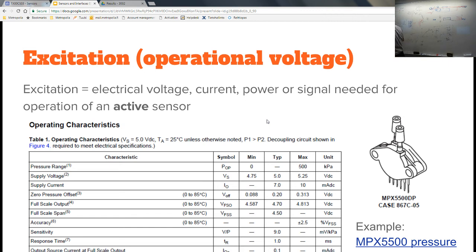Those are big membranes. One is solid, one has holes so that the air can go through. But anyways, you usually have an excitation voltage here, and this goes to some way of measuring the current. The distance changes, meaning that it changes the capacitance. If you have a capacitance change on constant voltage, you have a current.